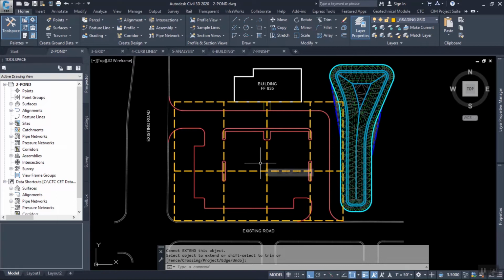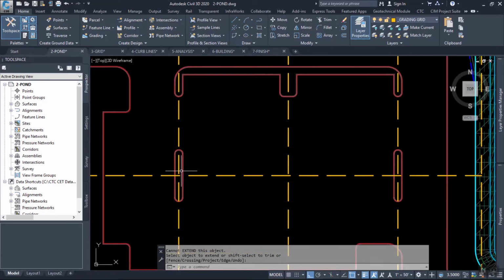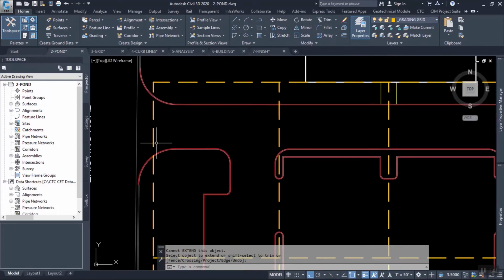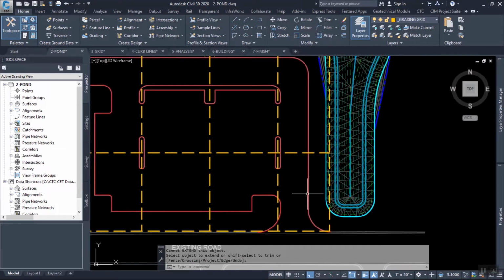I'm going to leave it fairly simple because we have only so much time. But what I'm looking at is I'm draining towards catch basins at these curb islands here. Obviously, I'm draining away from the building here. I've got a tie-in over here. I've got a tie-in over here. Okay, there's a lot of little considerations beyond just this.